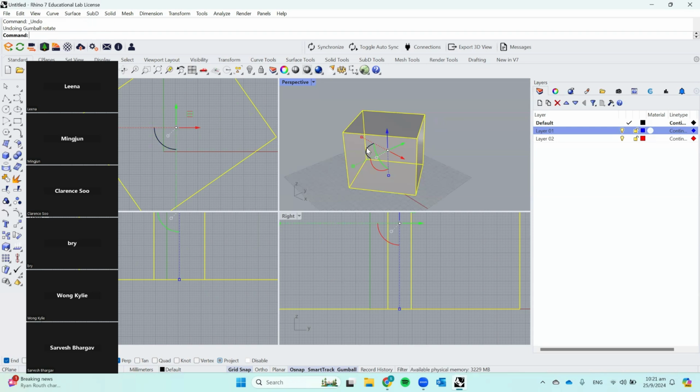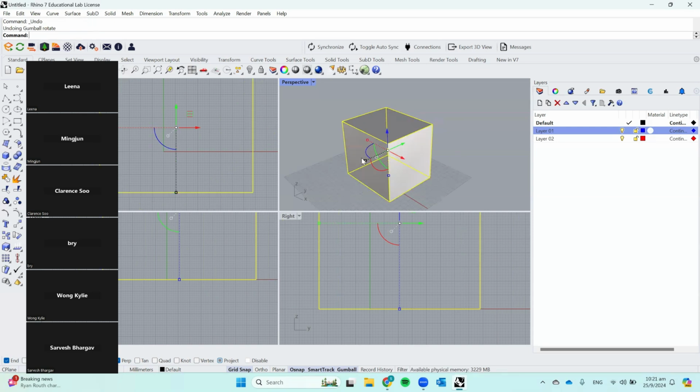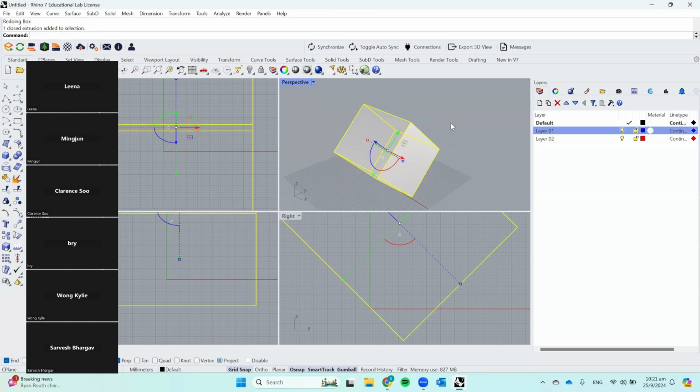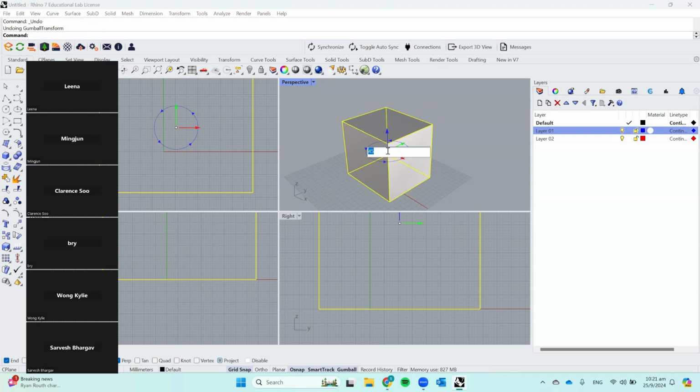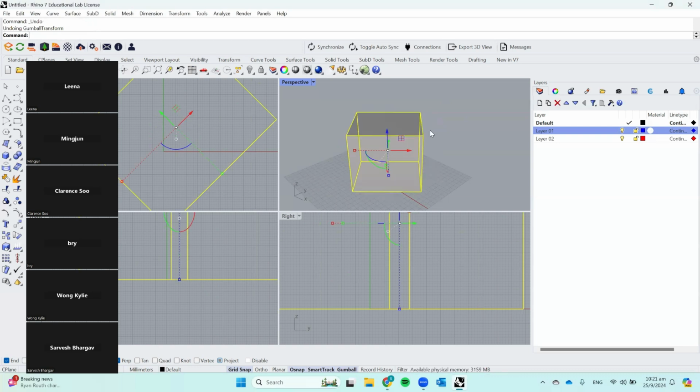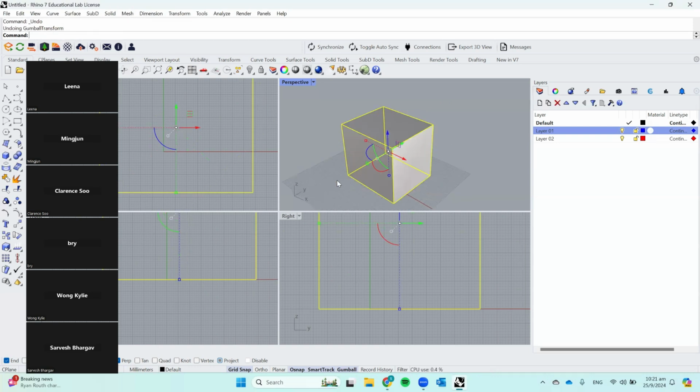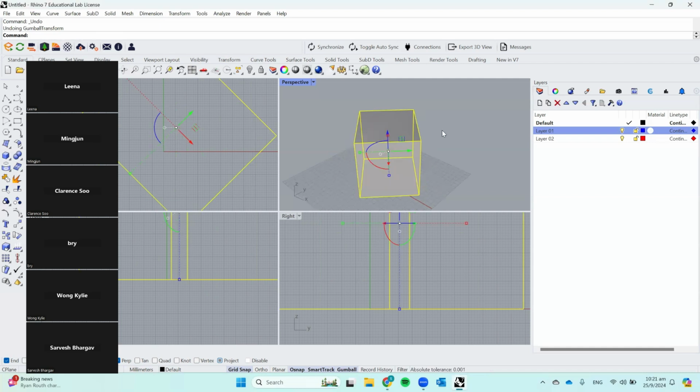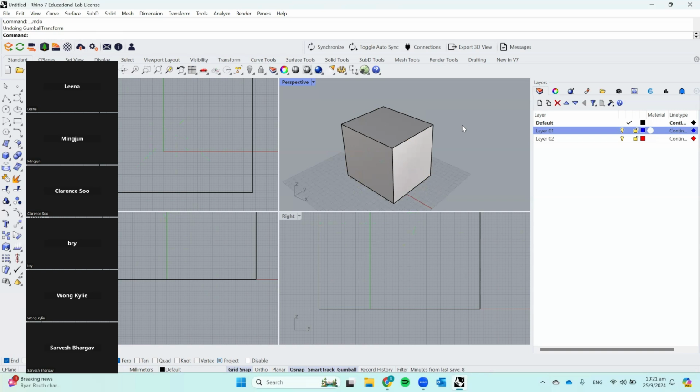And again, if I want to key in a specific number or a specific angle that I want it to rotate from, then I can click on this rounded thing and type in 45, then it will rotate. Or if I want it to rotate this way, I do 45 this way, or I can do -45. Same thing applies. Okay, so that is Gumball.